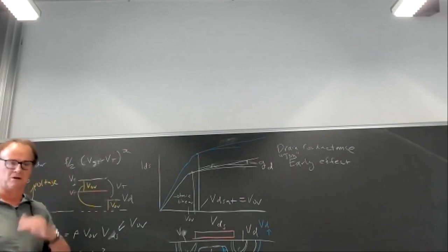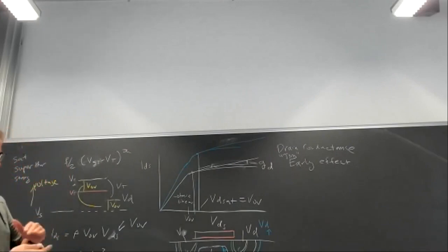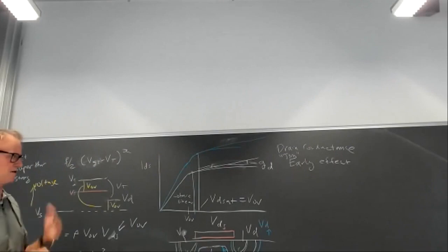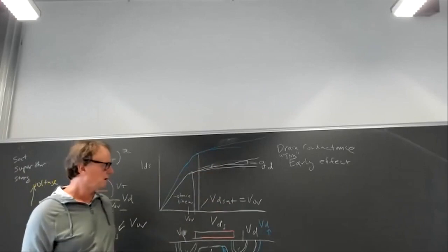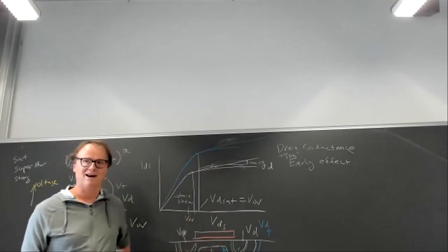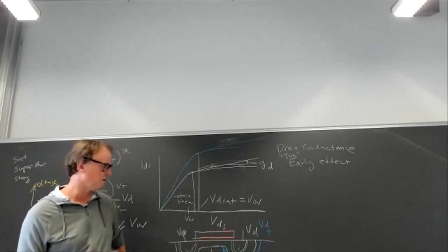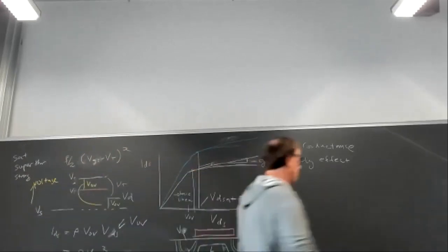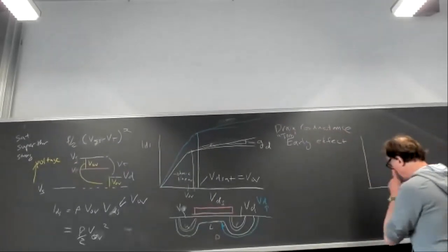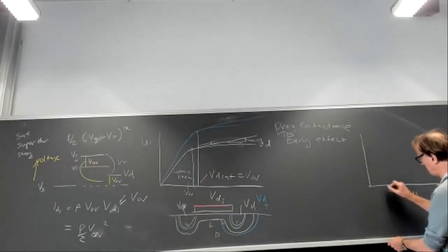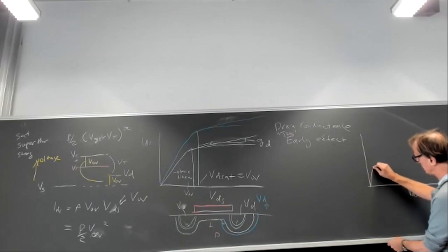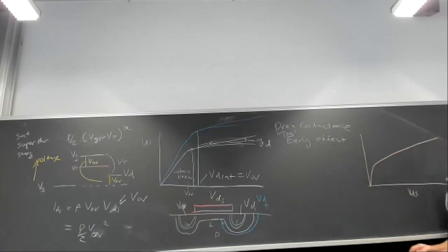In bulk PNP transistors, the same effect happens at the base, which changes as a function of the applied reverse voltage. So this Early effect is caused by the transistor channel getting shorter. Since it's a geometrical effect like that, it actually has really interesting behavior. If you plot it, take one transistor saturation curve, let's exaggerate it. Actually, it's not exaggerated. If you make a really short transistor, you can have a considerable slope on it.